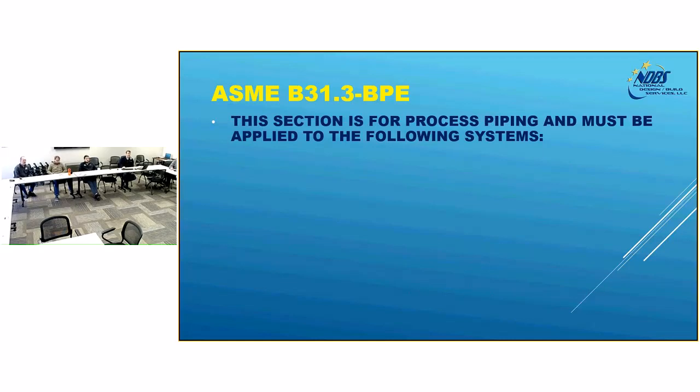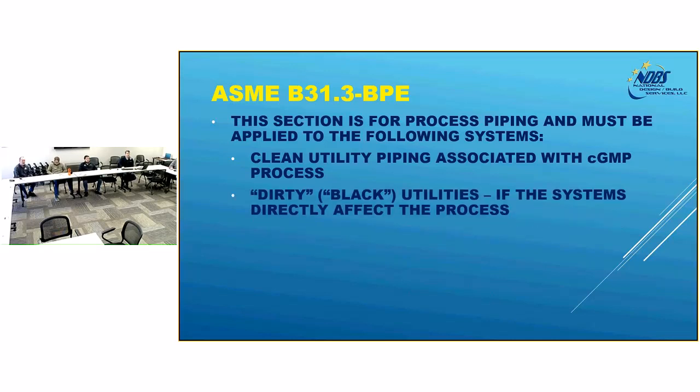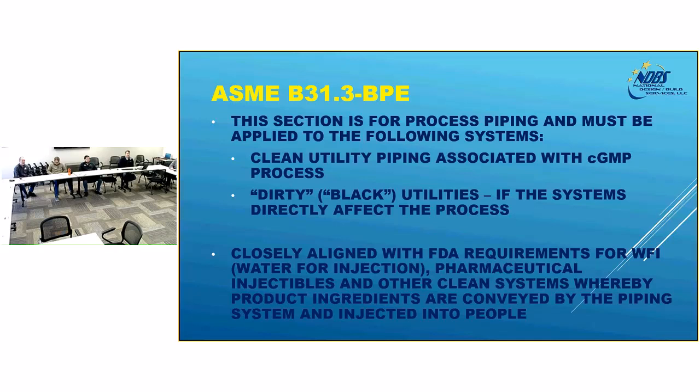For BPE, so this is also part of B31.3. Anytime you have a clean utility system that follows current good manufacturing practices, you're going to need to think about BPE. And here I kind of touched on clean utilities versus black utilities. There's a spec break there. There may be different testing requirements.